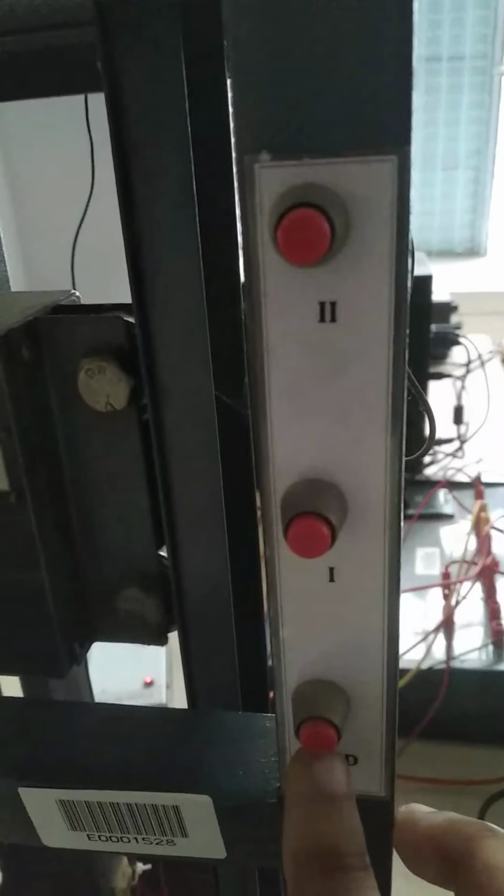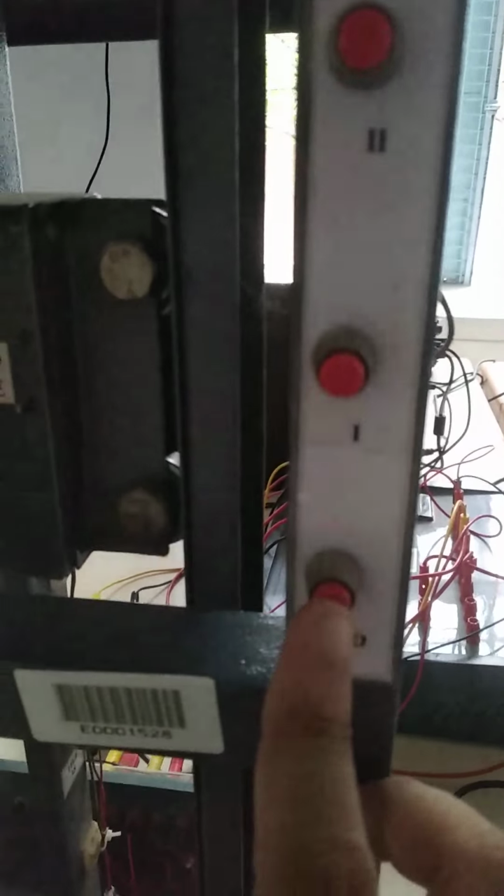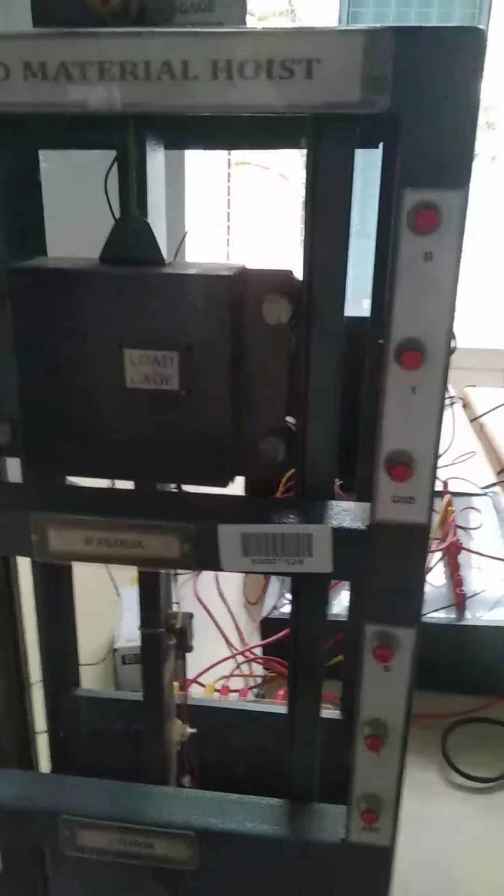Now if you see the inputs available in the setup, in each and every floor 3 push buttons are there. In the second floor you have 3 buttons, that is ground floor, first floor as well as second floor. Similarly, in the first floor also you have 3 push buttons. In the ground floor also you have 3 push buttons. The ground floor push button will be connected in parallel with the ground floor push button in other floors also. So even though you have 9 push buttons, effectively from the programming point of view, you have only 3 inputs.